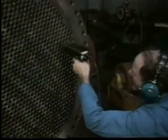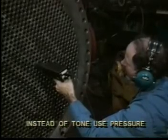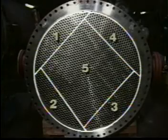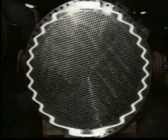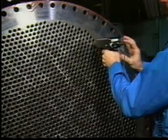In certain situations, it may not be possible to use the tone method. In these instances, use the pressure method. In peripheral areas, create zones for comparison testing of tubes with similar intensity readings and sound quality. Since tone generators are on top of peripheral tubes, they will be vibrated during testing of areas near the generators. For an accurate test, test one zone at a time.